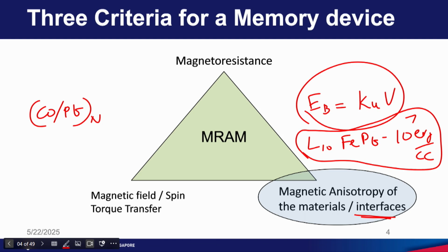Okay. So, any anisotropy is okay, as long as there is an anisotropy and the material has a certain volume. In the case of MRAM, this volume is basically the cylinder's volume. So, we are having devices in the form of a cylinder. You know the diameter, you know the thickness, you can calculate the volume. This volume multiplied by Ku gives rise to the anisotropy energy, and that is what helps us to store the information.